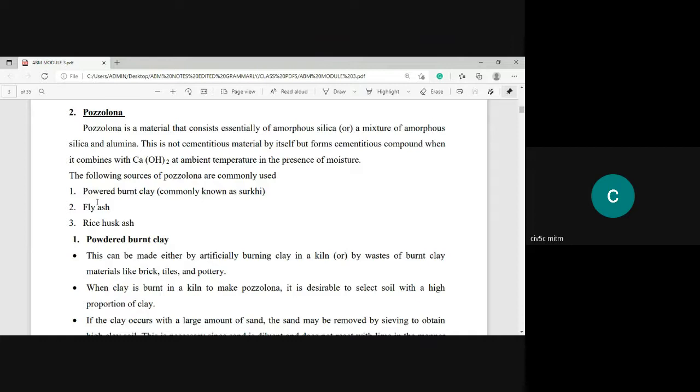So whatever the cement bag you people are getting nowadays, that is PPC. They used to say PPC. That is Portland Pozzolana Cement. So that pozzolanic material they are using inside the cement, or they are replacing the cement with, is fly ash. I will talk more about these materials in this particular module, because we need to thoroughly understand what fly ash is, how it functions, everything.